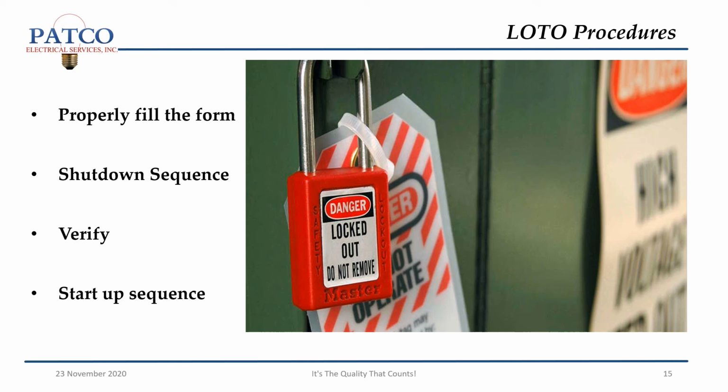Energy source isolated, and how. Did you isolate the energy source, and how? Stored energy relief: say you're working on a conveyor belt somewhere and you get your energy source isolated and have your lockout devices applied. Go back there, flip the switch, turn it on, see how much it moves and if it stops. If it moves and then stops, then you've relieved any stored energy. And always check the electrical power source with a voltmeter to verify that the power is off.